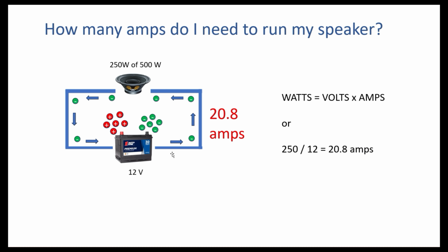Okay, so happy days, right? So we need 20.8 amps of current flow to maintain 12 volts of power at this speaker to run it at 250 watts.